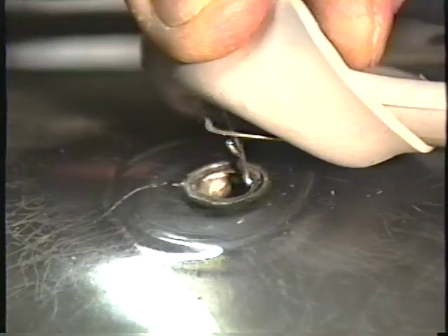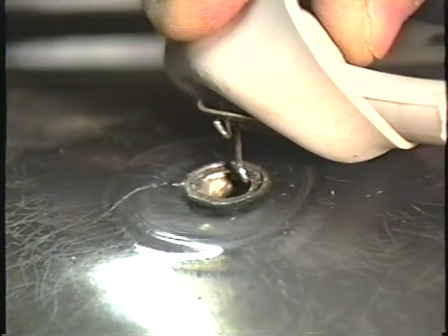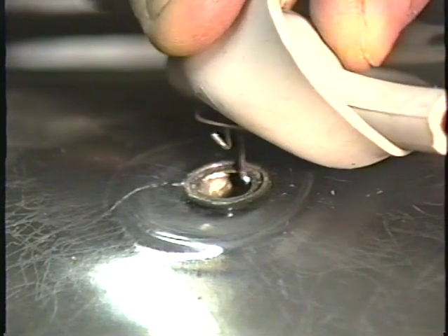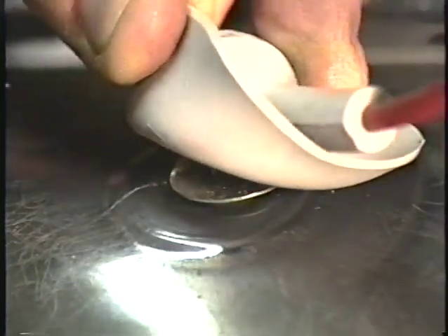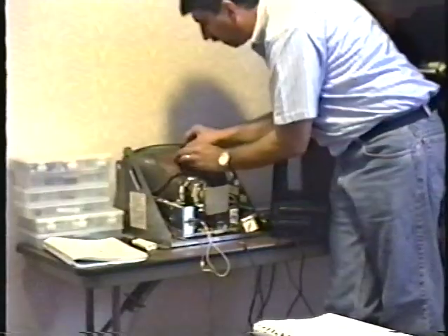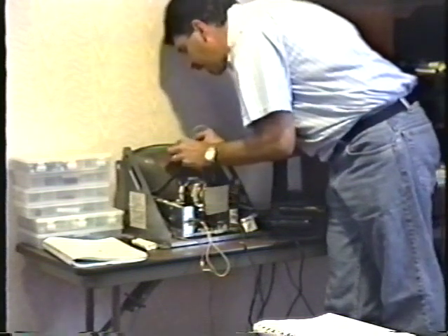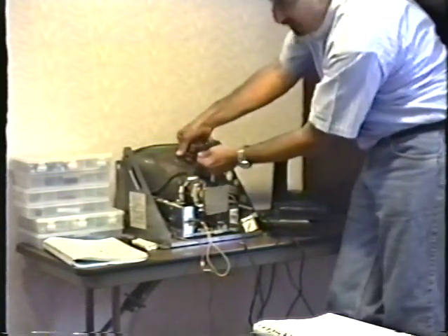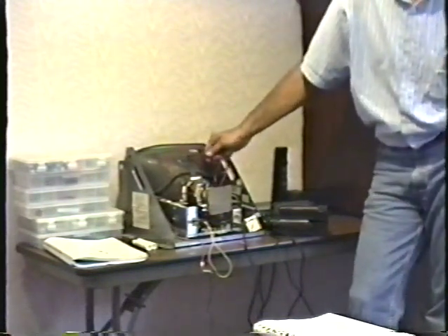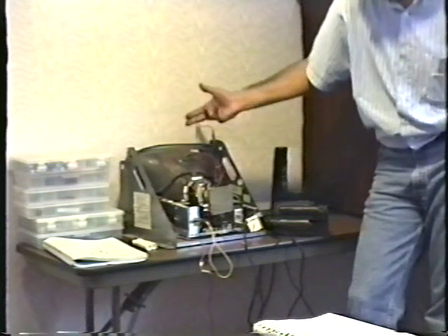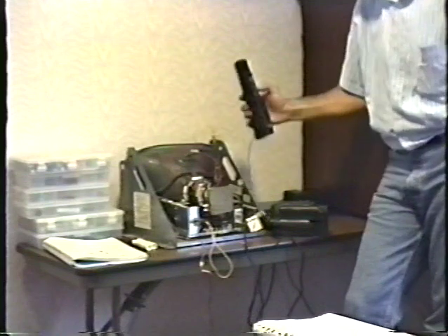Now it's kind of hard for me to juggle the camera and this at the same time, but basically what you do is this. Holding it like this, you put in one side, and then use the grounded screwdriver to shove the other side in there. When you get it in there, look at it carefully. Tug on it, make sure that it's in there. Some people pull the wire like this and pull it tight. Don't be afraid to tug on this thing. If it comes off in your hand, it wasn't in there properly. You should be able to tug on that and have it stay in there, and then it's okay.